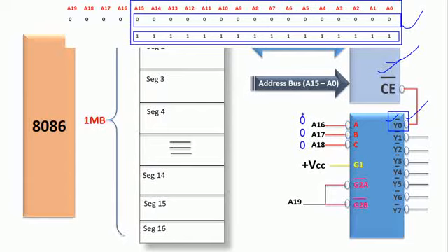Okay, so if you are applying the 3 zeros at the input of the address decoder, then output is the Y0 output line. We are having the 8 output lines. Out of 8, Y0 is going to be enabled. But in order to enable the Y0, along with these input combinations, you are supposed to activate the activating signals. Now, one of the activating signals is already activated, and another activating signal is an active low signal. You can activate these active low signals by applying the binary 0.